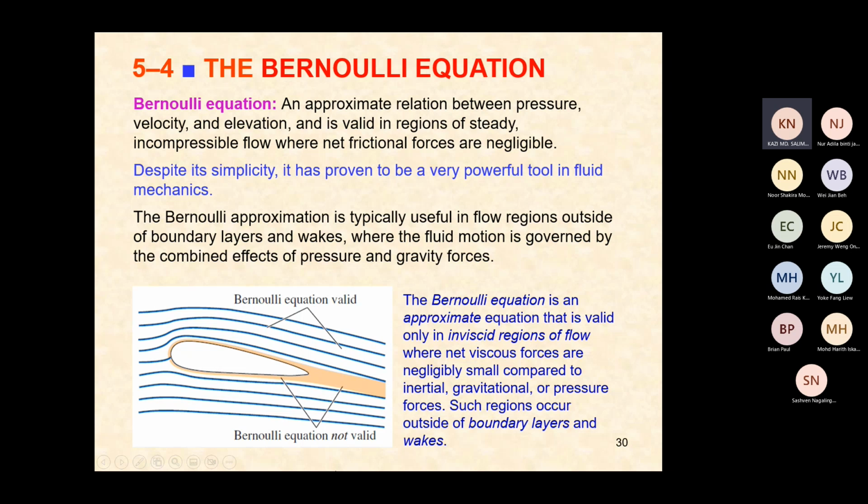So we can say that the Bernoulli's equation is really an approximate equation that is valid only in inviscid regions of flow, where net viscous forces are negligibly small compared to inertia, gravitational, or pressure forces, such as regions that occur outside the boundary layers.